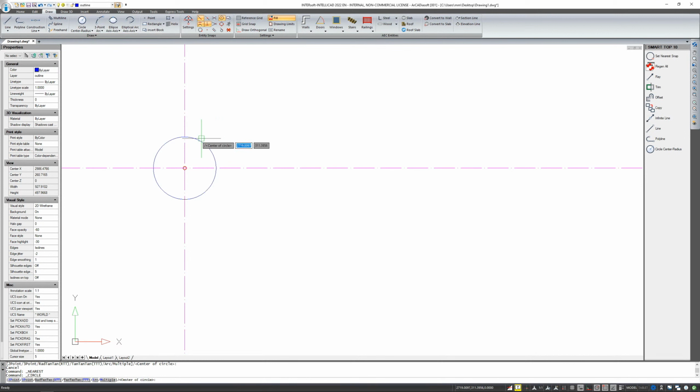Therefore, it would be best to disable these snap points and only use the most frequently used ones. I suggest that the nearest snap be turned off. The nearest snap point, that is the one that shows around the entire circle along the length of the line, is not a very precise snap point. But please note, if you start to draw a circle again, and I have turned off this nearest snap point, then without any problem, even without zooming in too closely to the drawing, this center point of the circle is very easy to snap to by the program.